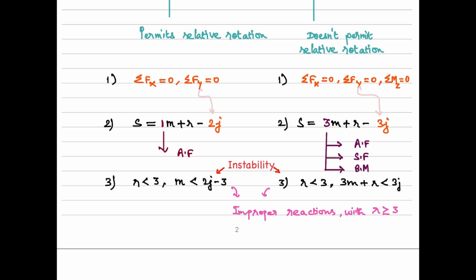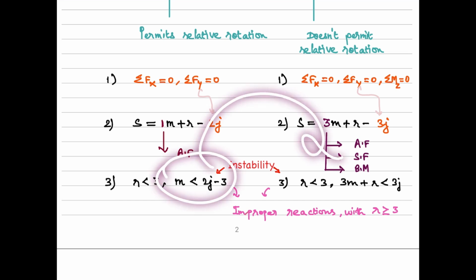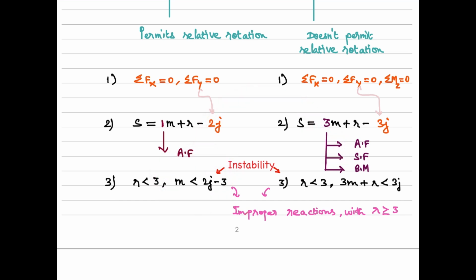We can't just extend this idea here, because I have already told that the idea of triangulation is not applicable to a frame. However, we can have an analogy here. In a frame, if any member or any joint contains excessive internal releases such as an internal hinge, in that case, it can also lead to instability. We will understand this better when we relate this with an example. I'm not getting into this further.